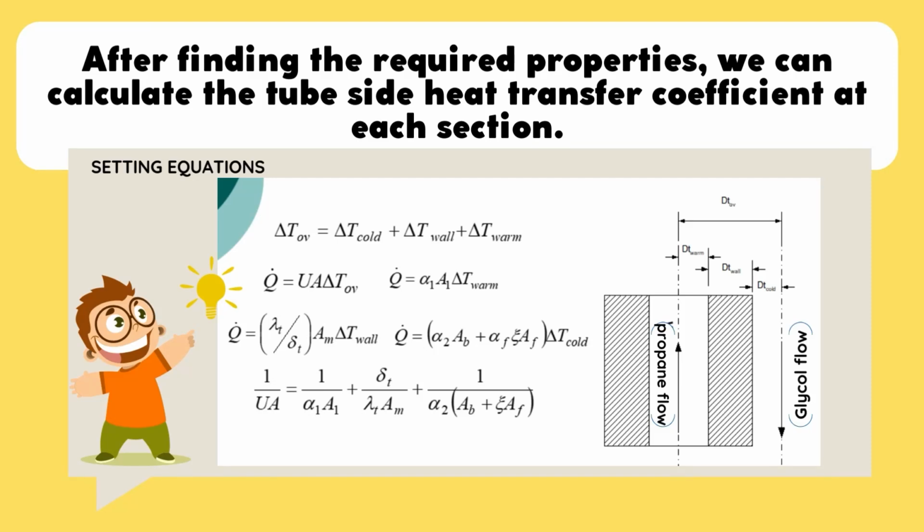First, the mass flow rate of propane was calculated for each section. Then, the enthalpy values for each section were determined. This process was repeated for all 248 experiments. A polynomial curve was assumed as the best fit to represent the temperature variation of glycol. Afterward, the 2-phase length was calculated for each section. Finally, the propane temperature variations were calculated, assuming 2 different linear variations, one for the 2-phase region and another for the superheated phase.